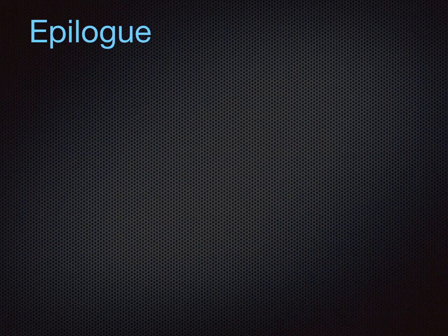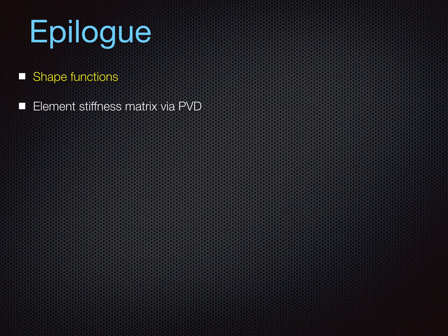So that concludes our discussion of the principle of virtual displacements and its application to frame problems at hand. We have discussed the shape functions, how they are rearranged to have their generalized coordinates represent physical quantities like nodal displacements and rotations. We have used shape functions and exercised them through the principle of virtual displacements to obtain the element stiffness matrix.